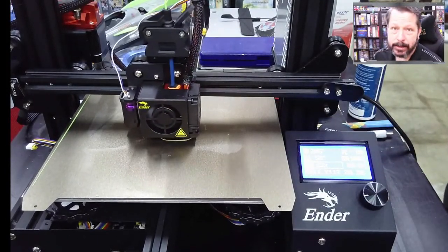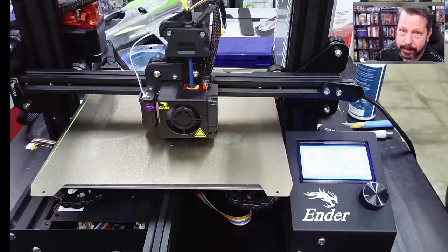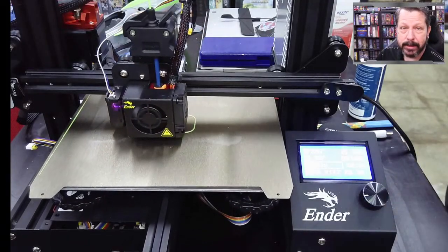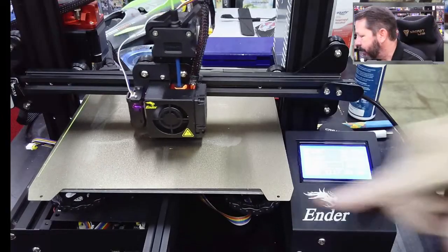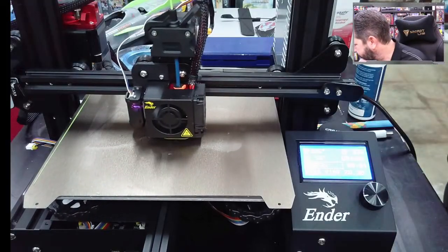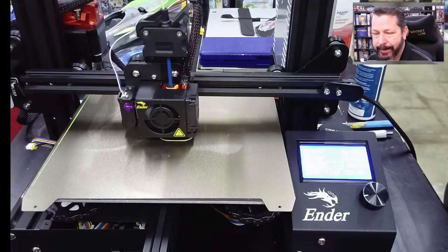If you are using the whole bed to print, that's when you need to start making sure your bed is as flat as possible. You might even want to switch to a glass bed so that it is flat, like a piece of glass, versus potentially bowed or whatever that the metal can be. So it does have to print some bottom layers. I think I had it set to 2.